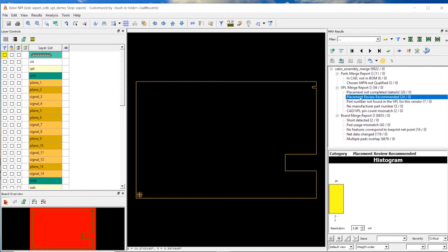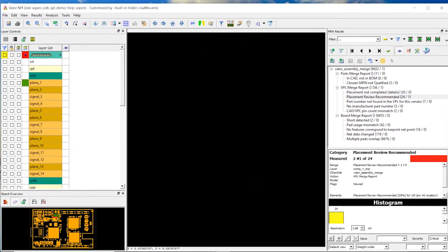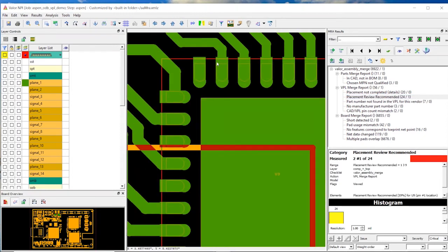I have set this up to automatically mount the component the best it can on the board. Okay, the placement review is saying it ran into some issues doing that, and maybe you should review this possibility. So if I go like this and look, if I scroll in, it might be hard for you to see, but the pin location is superimposed on the pad location.